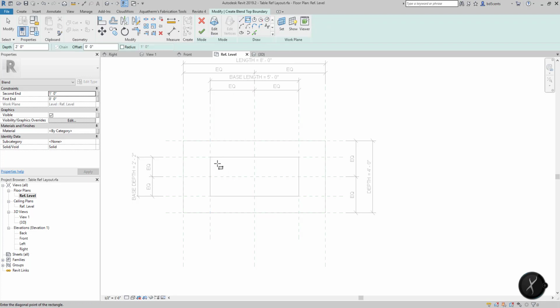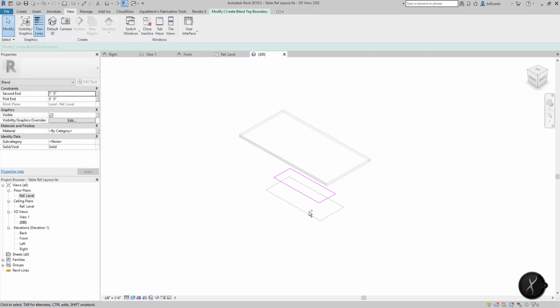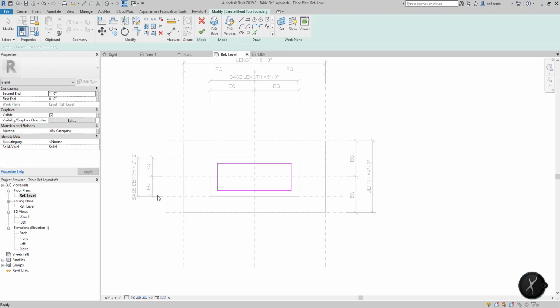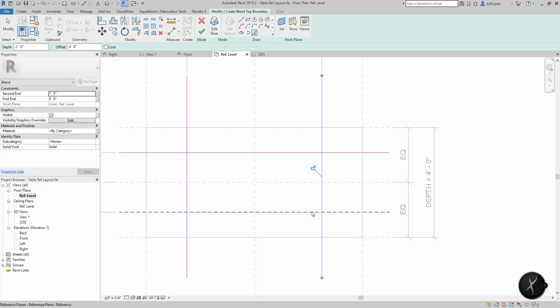which means if I draw the top base reference plane as a smaller box, something like, say, this, then if I view this in 3D, I can see that the associative level is changed. So that value has changed. So going to reference plane 1, I could create a trapezoidal feature. So I could actually, rather than selecting that, select all the lines from below, reference planes in this case, trim them together to create that top.